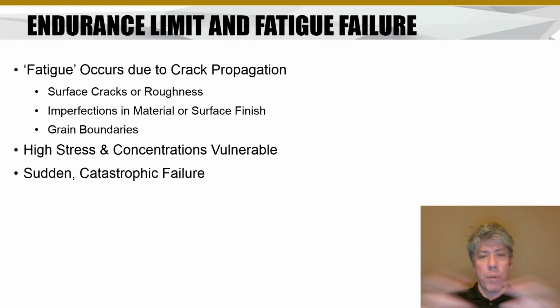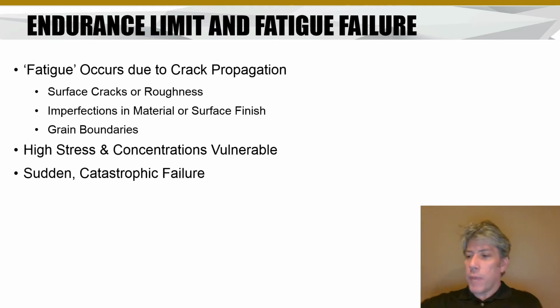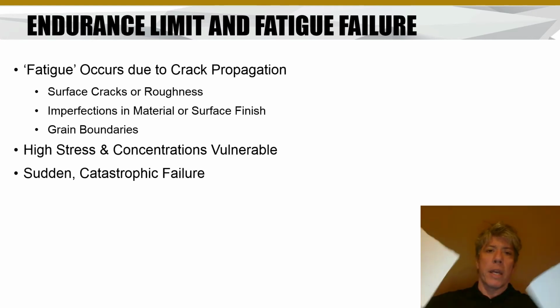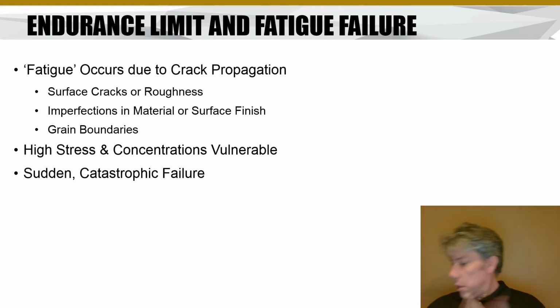If you make a part, the surface is not going to be perfect. There might be cracks just in the surface. There could be even roughness in the surface that can provide a small enough crack where there's enough stress concentration that the crack can open every time it's pulled apart. Basically what happens, think about a piece of paper, for example, where the piece of paper has a very small rip in it. If you start applying tension to this over and over and over, you eventually break it. Right? You eventually get to a point where it just can't take the load anymore. And so that's essentially what happens with metals.